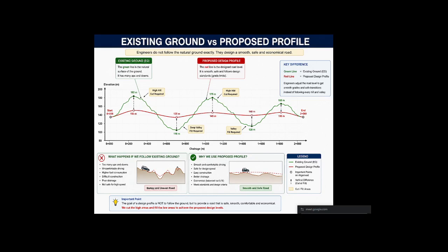See, now the horizontal distance is 100 meter. Now we don't rise, we fall by 5 meter. And now I have to give the grade. Then how much grade do we give? First, sir, the grade percentage is vertical height divided by horizontal distance, multiplied by 100. Right, sir? Right.